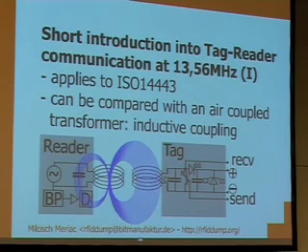You see also the part with D1, C2, and Z1, which gets the power supply part of the signal. Basically, it's a simplified schematic you see here. Normally you have a bridge rectifier, so you get more power. In this case, you only get the upper part of the wave, and it's basically rectified with D1. It's smoothed by using C2, and Z1 makes sure that the chip doesn't die, because if we get too near to the reader, you can get several hundred volts coming out.